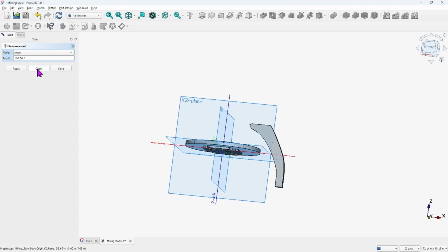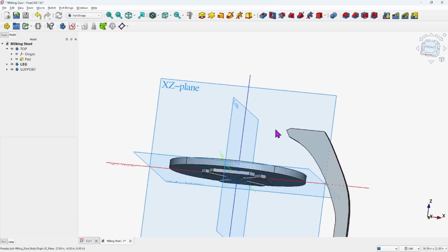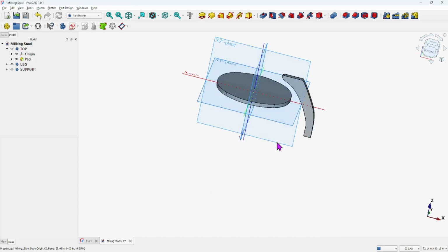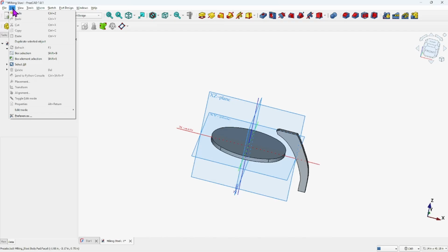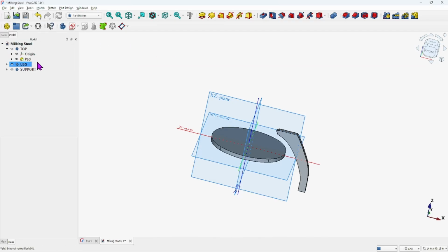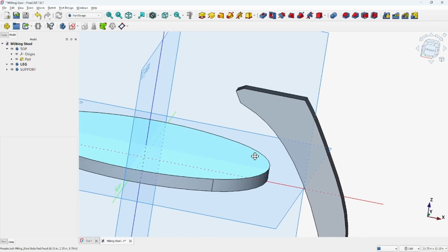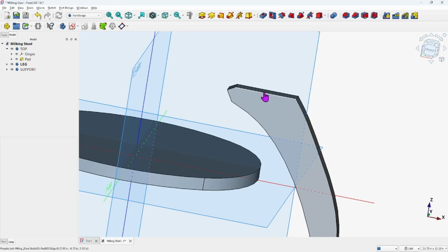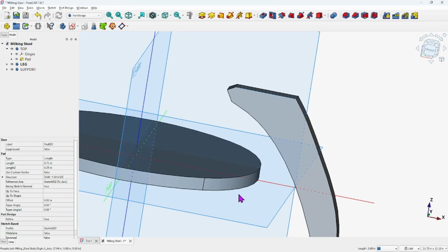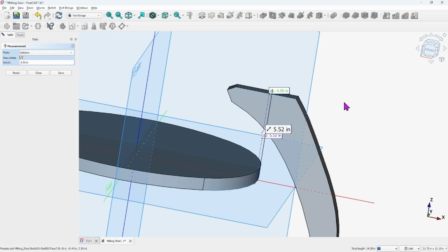And it's on angle. All right, I'm going to close out. I think the computation is messing it up again. Let's see if I can do a refresh. No, it doesn't require that. We'll try it again. If it doesn't work, then I'm going to have to turn the computer off and back on. This time I'm going to use the lines instead of the face. So there, that line, hold down the Control key and select that line. Hit that, and there we go. That's all I wanted. All I wanted was the dimension on the Z.